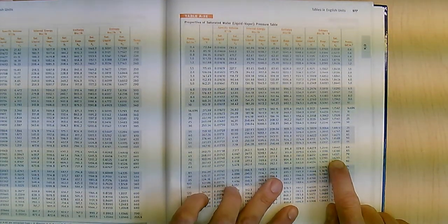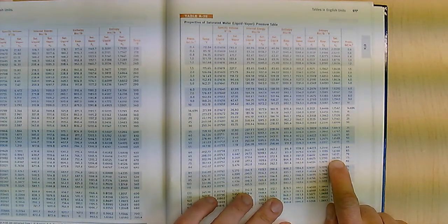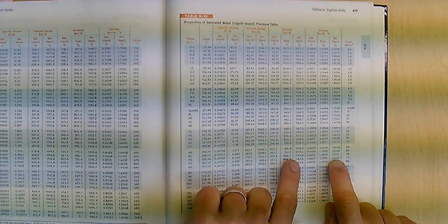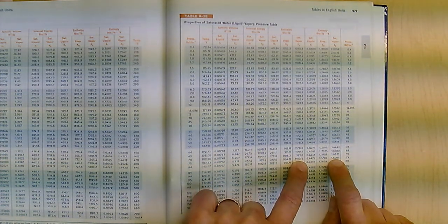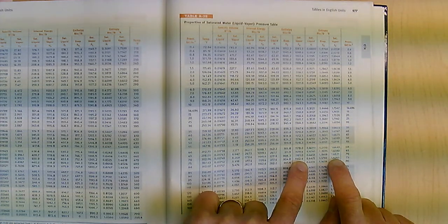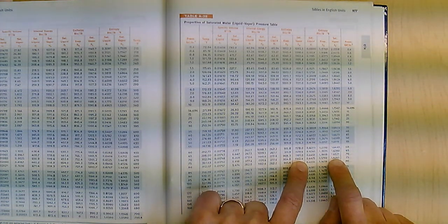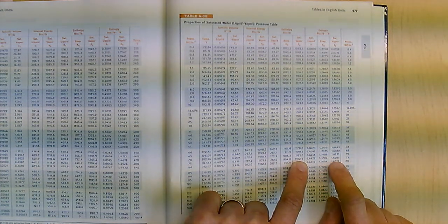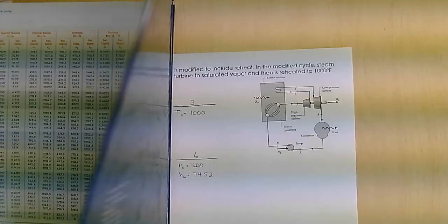In actuality, when I do my interpolation, it's 70.5 psi, and that corresponds to an enthalpy of 1181.1. So that's where I am at state 2. Again, I know I'm at saturated vapor at 1.6315 entropy.